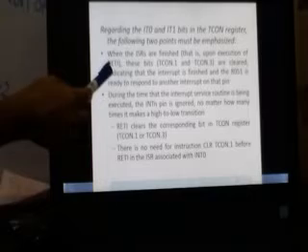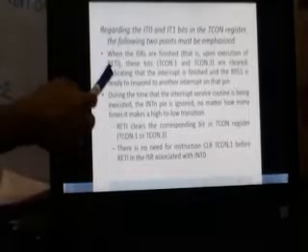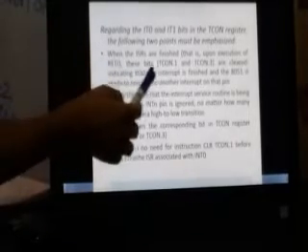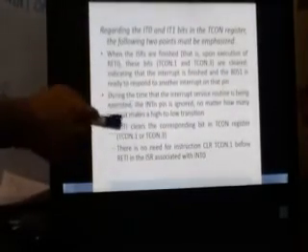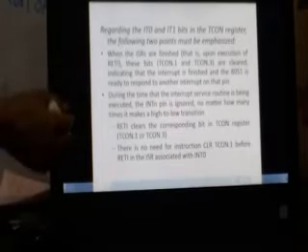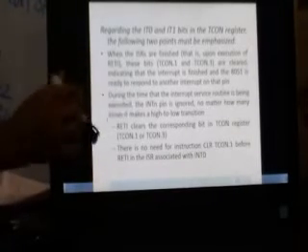I told you this already. They become clear when RETI is executed, indicating that the interrupt is finished and the 8051 is ready to respond to another interrupt. During the time when the interrupt routine is being served, there should not be an interrupt within an interrupt.